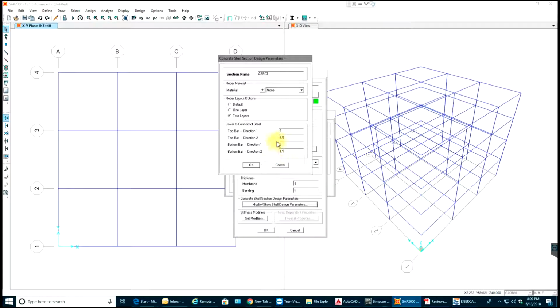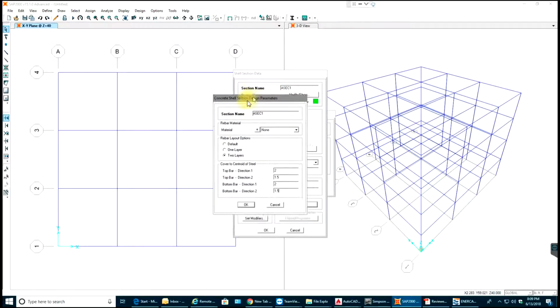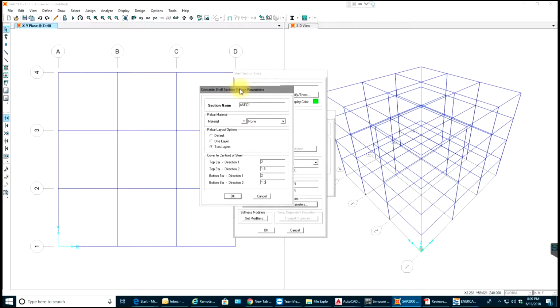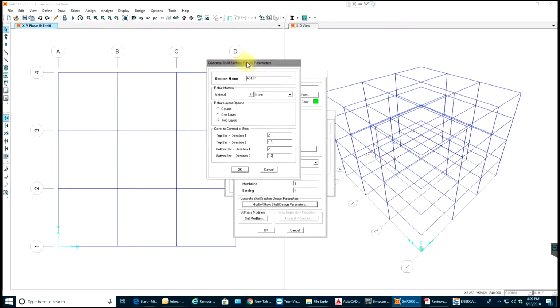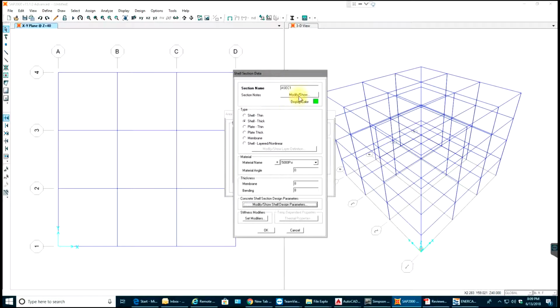So always, guys, make sure that you enter your correct data, because in the last 2 video tutorials I made some mistakes. In the RCC building video tutorial I entered loads in kips instead of pounds, and I got deflections like 600 inches, which scared me, and I was wondering where I was wrong. But later on I figured it out, and it was in the load.